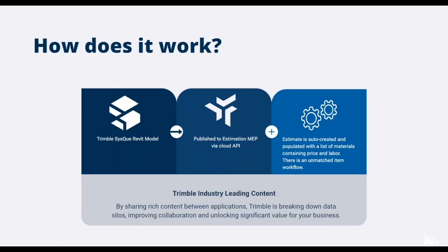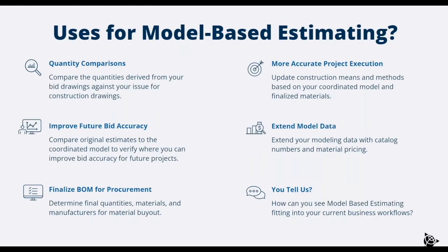So how does model-based estimating work? Well, we've been talking about Trimble SysQue here, which is powering a model-based estimating workflow. And we'll run you through it real quick. We'll select some model objects. We will then send those to model-based estimating, which is then received by our estimation MEP product. And then we're able to view that estimate and act on it. And then eventually we're going to use that same estimate, and we can send it straight to procurement from SysQue, which we'll look at in a sec here.